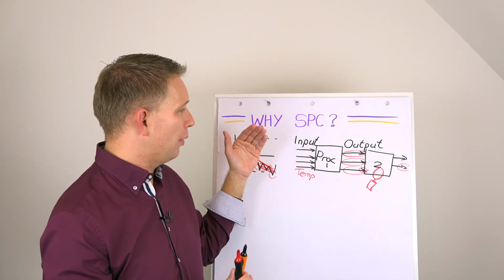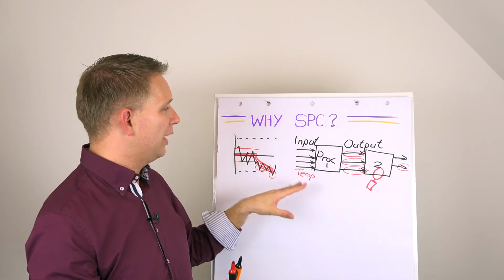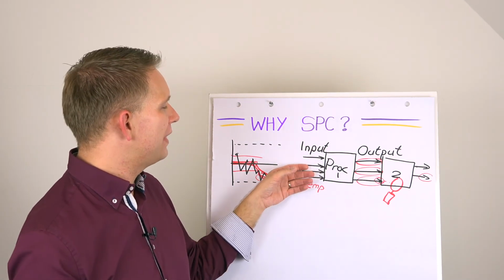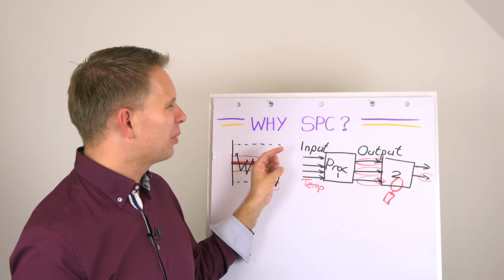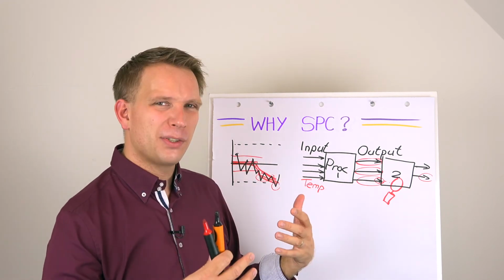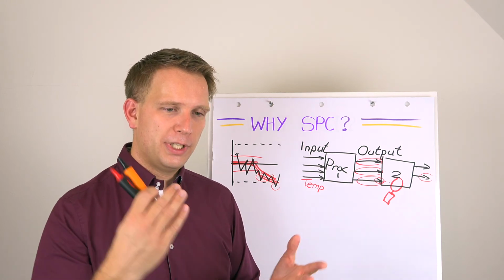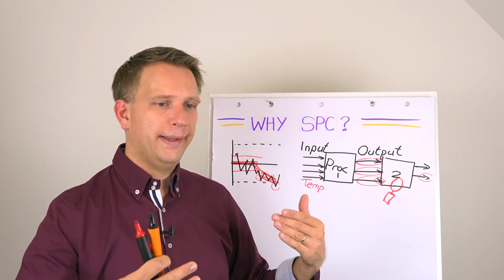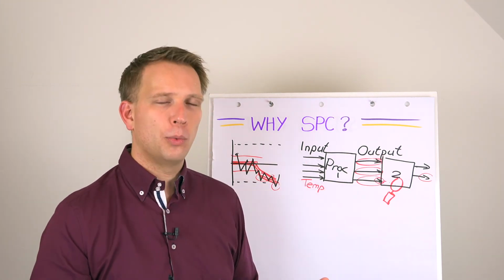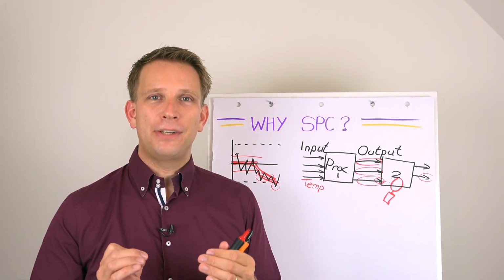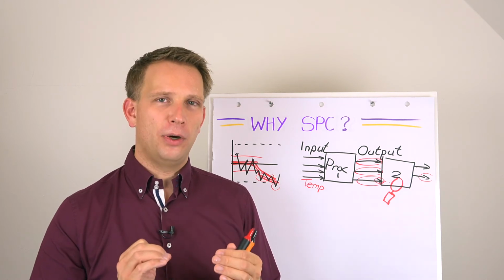We are checking our processes. And for that, we can check inputs. We can definitely check outputs. With the inputs, don't check purchased materials so much. That's not very interesting. Check things like what are the temperature and the pressure settings that I put in, what is happening with process parameters. For outputs, check anything that is a quality parameter of your product.